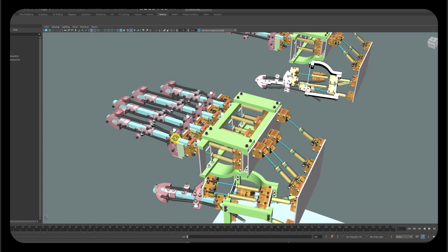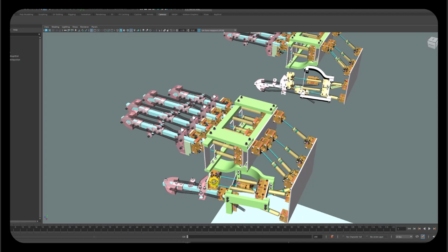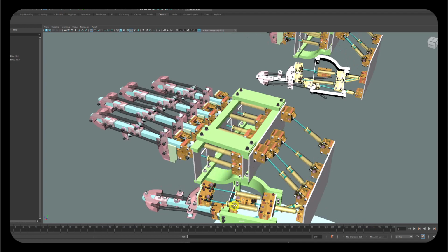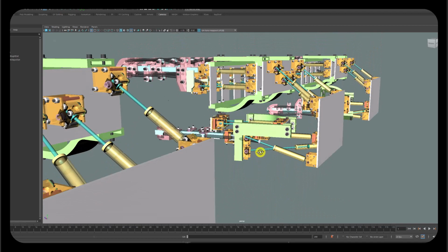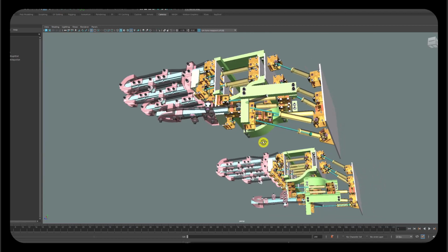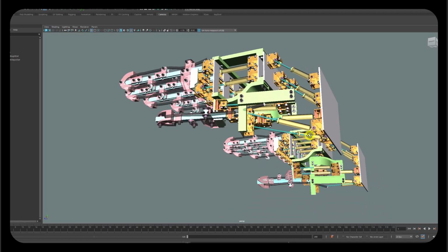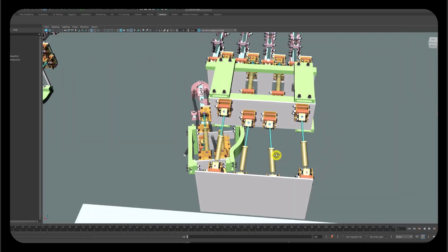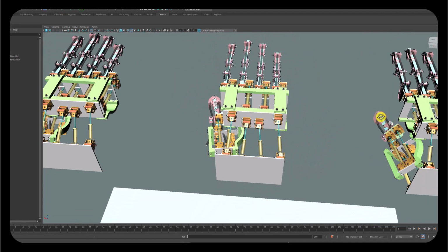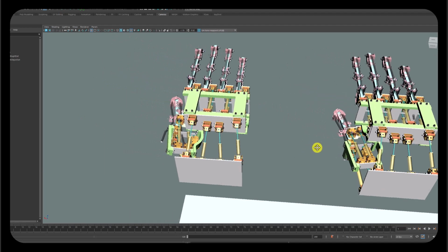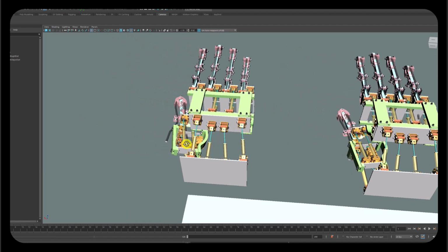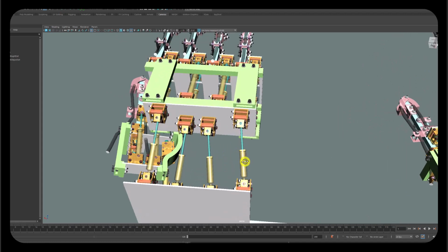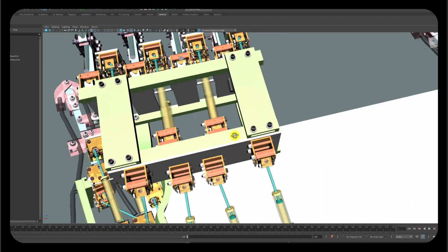Here's the two hydraulic cylinders that control the fingers, the intrinsic motions of the finger, and the thumb has that same two set of hydraulic cylinders, but it has a whole completely different set of three more hydraulic cylinders, and they can swing the thumb out laterally, so they can take it from here and move it to there, and they can move it even further this way and begin to swing it up out of the way. And these hydraulic cylinders articulate on a cardanic joint.